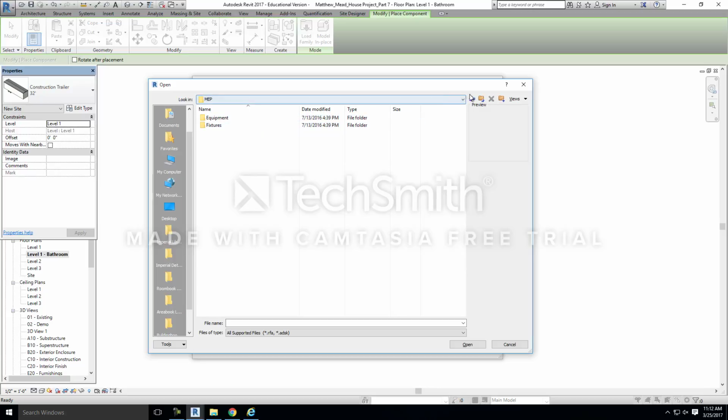Nothing all that exciting, but go through and look at it. There may be some objects in there that might be useful to your bathroom. But for now I'm just going to click on Architectural, and then click on Fixtures, and you'll see from there it breaks it down to bathtubs, drains, drinking fountains, showers, etc. You'll have all kinds of different stuff. I'm going to start with bathtubs.